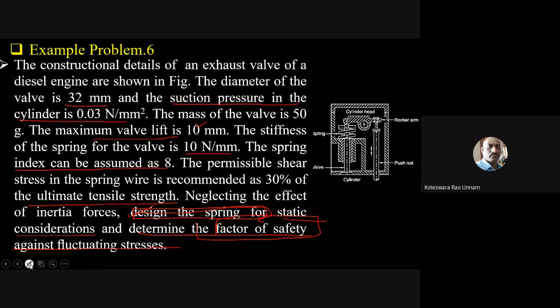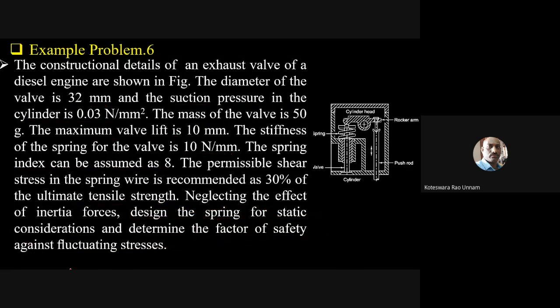That means first you need to design the spring for the static loading, then you need to check what is the factor of safety, whether it is as per the requirement or not. So the first part is the static design of the spring under static loading. Then the second part of the solution is you need to compute the factor of safety.